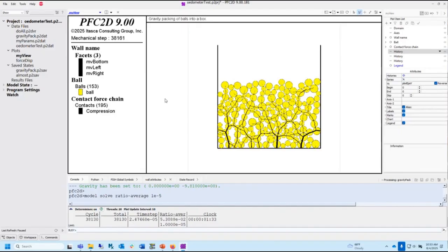For that type of question, it turns out that the stiffnesses of the particles have very little impact on the flow characteristics of the material. And so usually when people build granular models, they make the stiffnesses really, really low, unrealistic, but they don't care because they're going to get the right answer anyways, and the models run faster.